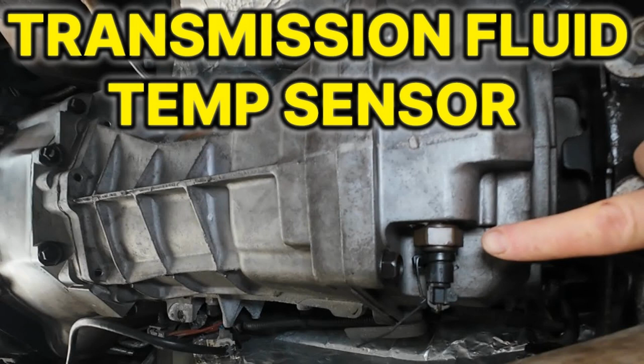2. Repair or replace faulty wiring. If wiring or connectivity problems are identified, repair or replace defective sections. This may involve soldering faulty connections, replacing damaged wiring harnesses, or repairing faulty connectors. Once repairs have been made, reset the system by clearing the fault codes.